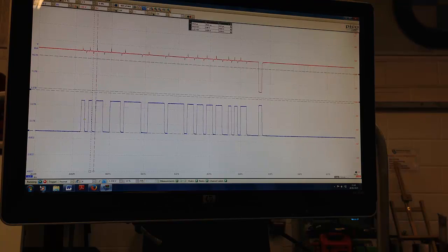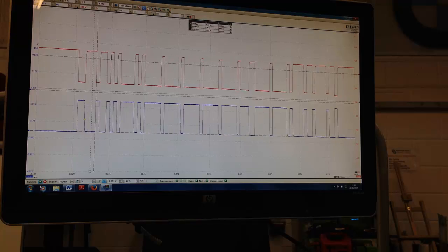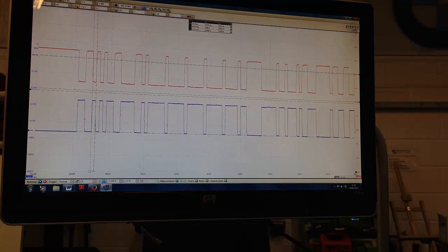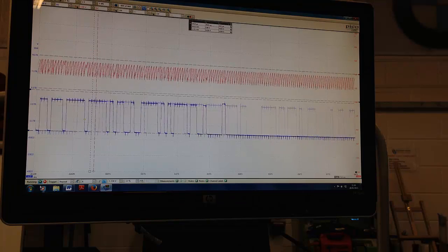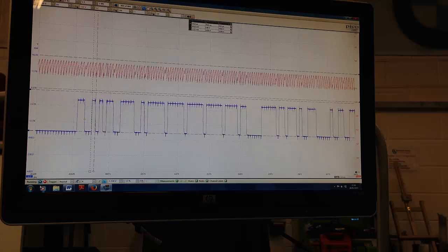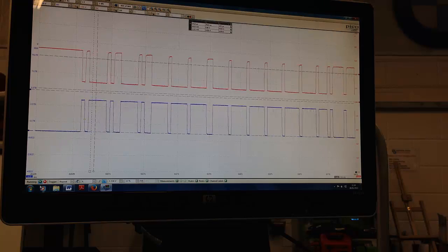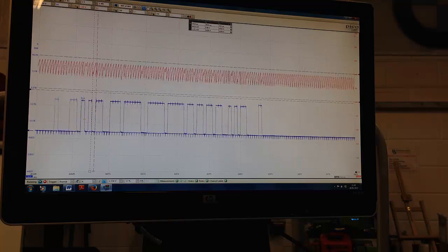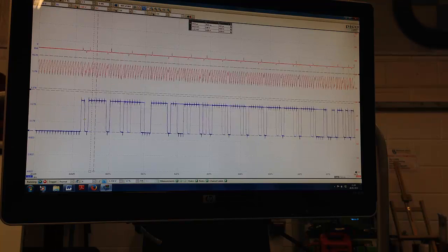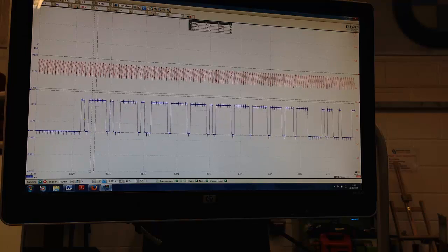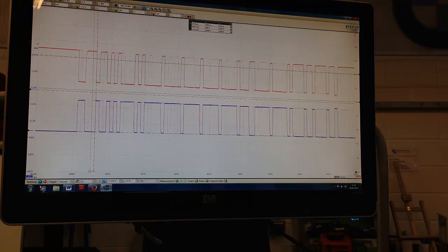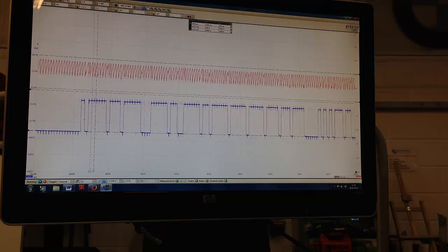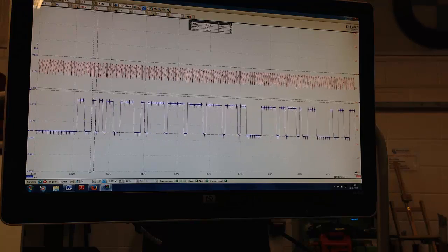Let's put the indicator on. Okay, so now I've got an indicator, and I've got my indicators back. Let's plug that connector back in. And the indicators aren't functioning. So we can almost play a tune on this. With it disconnected, CAN signal's good. Let's put the wipers on because that's probably easier to hear or see.